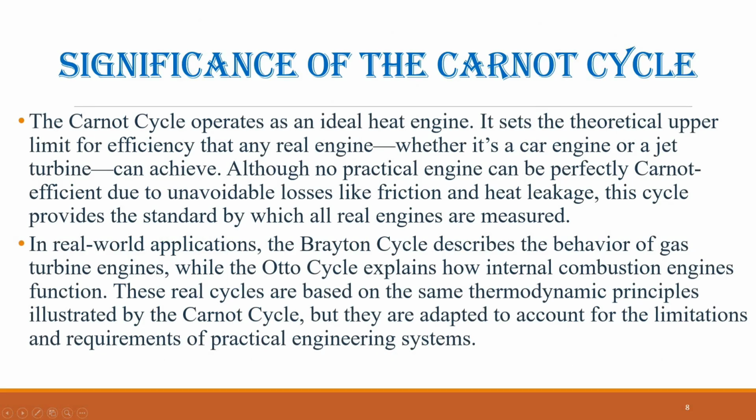Significance of the Carnot cycle. The Carnot cycle operates as an ideal heat engine. It sets the theoretical upper limit for efficiency that any real engine, whether it's a car engine or a jet turbine, can achieve. Although no practical engine can be perfectly Carnot efficient due to unavoidable losses like friction and heat leakage, this cycle provides the standard by which all real engines are measured.